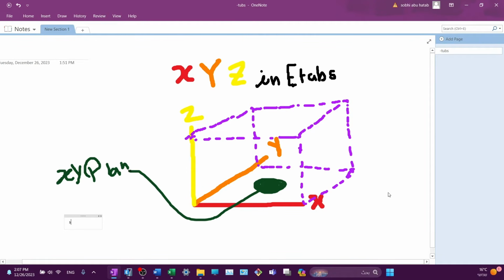Now we are going to talk about XYZ for the grid system in ETABS. X in this direction, Y out of the plane in the paper, out of your view, Z representing the floor heights, and XY plan or plane, this is XY plane, and the 3D view will show you X, Y, Z coordinates for the 3D view of the structure building.